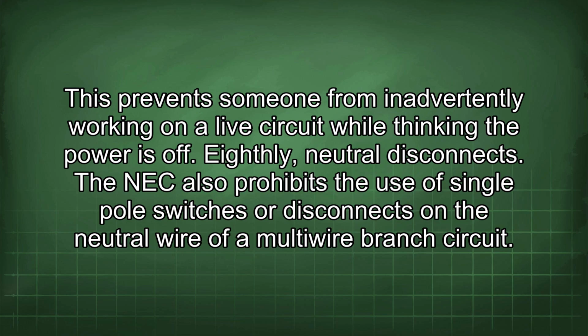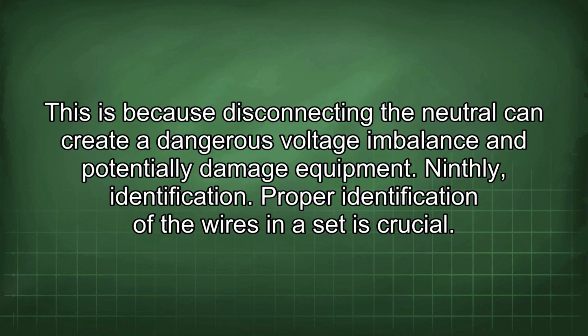Eighthly, neutral disconnects. The NEC also prohibits the use of single-pole switches or disconnects on the neutral wire of a multi-wire branch circuit. This is because disconnecting the neutral can create a dangerous voltage imbalance and potentially damage equipment.